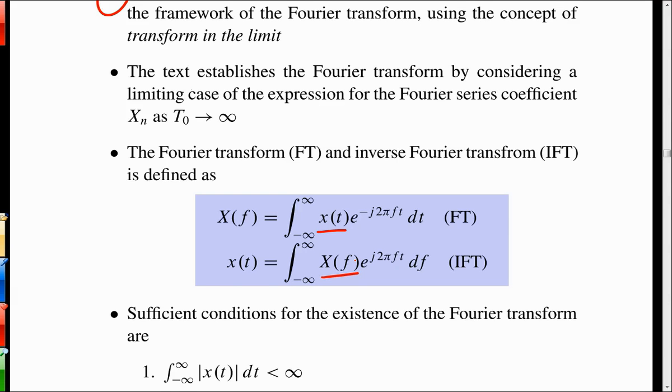Now, one of the things that might bother you, and that's what this bullet states, but in my book, my editors made me put in an example of this bullet right here. How do we get to the Fourier transform from the Fourier series? You can actually do this by taking your pulse train as an example, and if you keep the pulse width fixed and then let the period go to infinity, all those periods will slide all to infinity, and instead of having a series of pulses, you have just one isolated pulse.